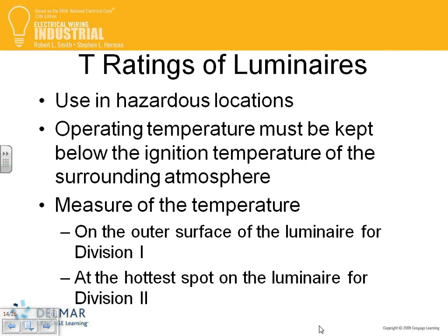T-rated equipment, guys. When equipment has lights, when they put luminaires, they have a T rating for them. It will tell you the surface temperature of this fixture. So if the surface temperature of this fixture when it's up and running is 100 Fahrenheit, and the ignition temperature needed for this gas is 90, then I can't put it in a place where it needs only 90 degrees to ignite the gas or the dust. So that's why it's very important. This was actually on the test, just FYI.